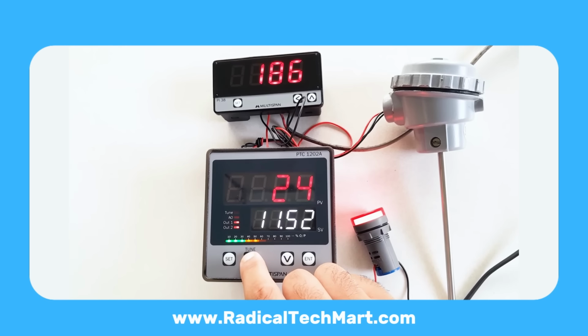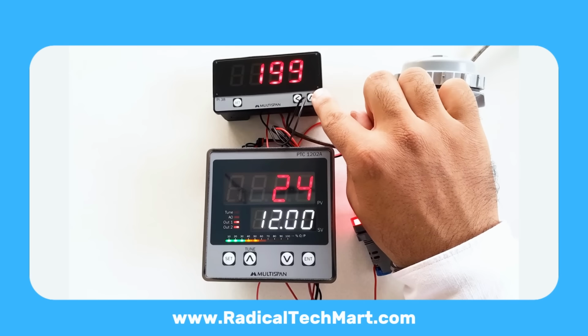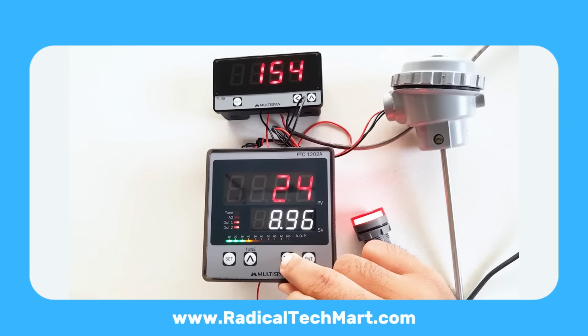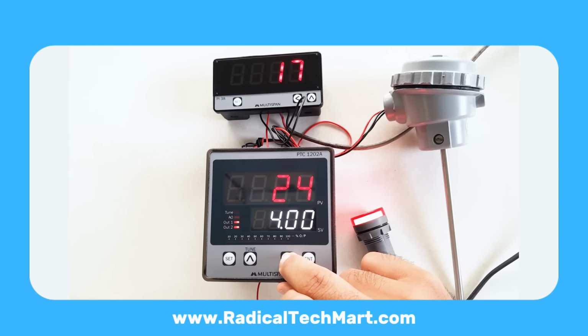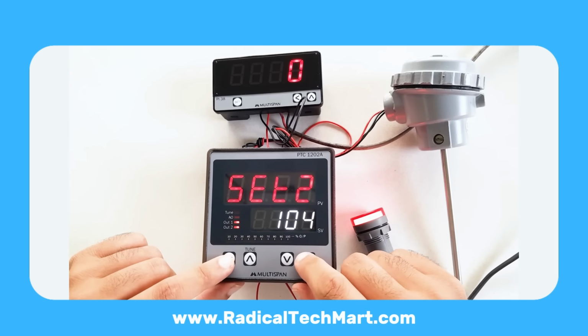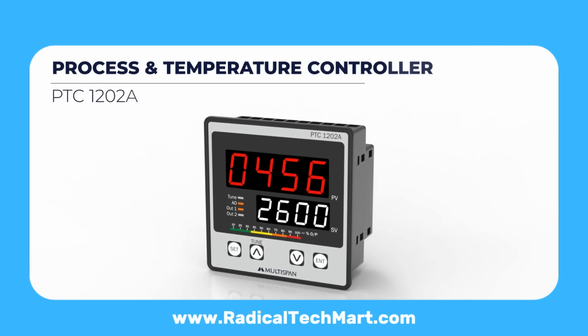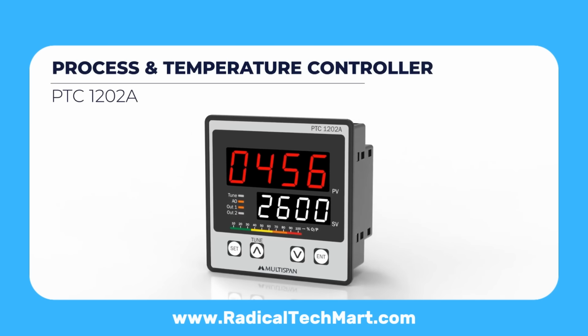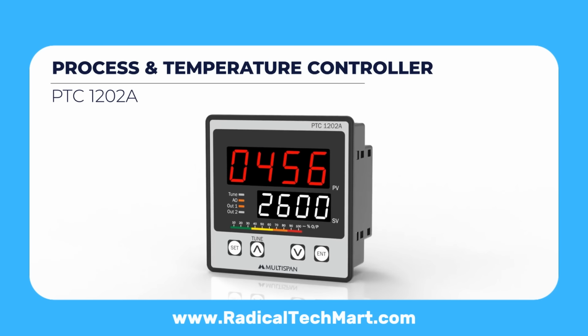Tap set to edit set 1, relay 1 SP. Because we set SLL equal to 10, set 1 won't go below 10 degrees Celsius. Tap set again for set 2, relay 2 SP, if R2 is used. Remember, SLL and SHL are guardrails for operators, preventing accidental set points outside the safe process range. That's the PTC-1202A: versatile inputs, built-in 24V loop power, dual relays, analog output for PID, retransmission, or manual 4 to 20 mA source, and straightforward menus for scaling and tuning.